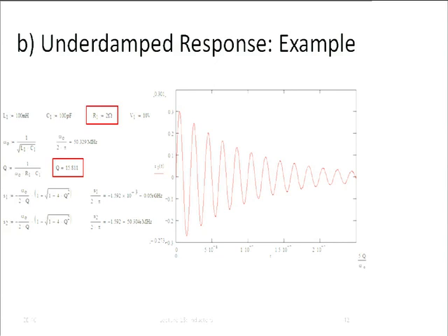For example, if we look at this picture, we see the exponential decay, but we see that it also rings. There is also an oscillation. It's not somehow a timer circuit or a synthesizer that made this. It's just a capacitor and an inductor together. If we hit them with a step, they can produce such waveforms. Okay, so those would be second order systems.